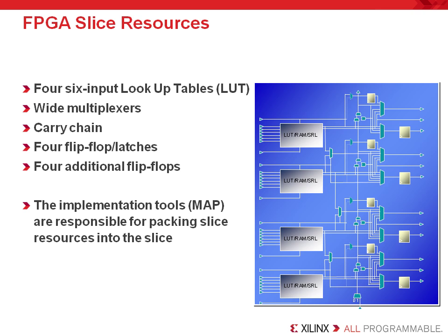Each CLB contains 2 slices. From this diagram, you can see that each slice has 4 LUTs, 4 flip-flops, and 4 additional flip-flops that can also be programmed as latches. The carry chain is connected to 4 of the 8 flip-flops. There are also dedicated muxes which can be used to build larger multiplexers and save LUTs so your system can run at a higher speed.